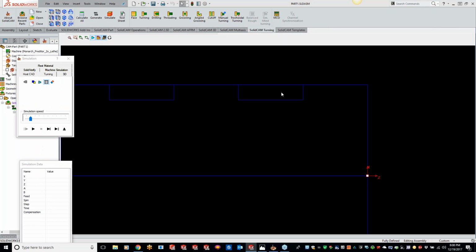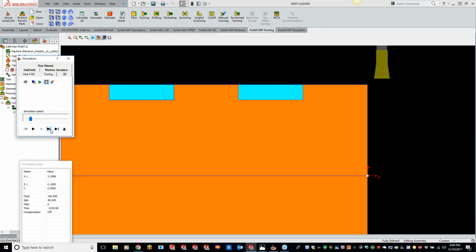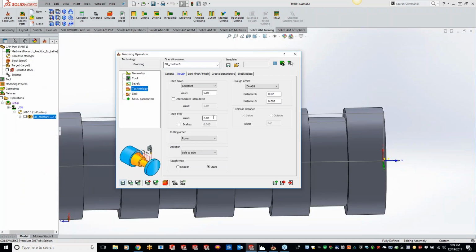And Ronnie, I'm working on that one so it comes in here for you, so it's not zoomed out at a reset point every time, which was a great idea. Okay, so we're coming in, and it's just doing a step over. Well, I can already tell that I am wasting a whole lot of time here. So let's increase our step over. So I'm going to bump that up to, let's try 200 thou here.